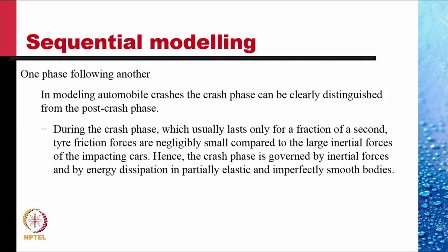During the crash phase, which usually lasts only for a fraction of a second, tire friction forces are negligibly small compared to the large inertial forces of the impacting cars. Hence, the crash phase is governed by inertial forces and by energy dissipation in partially elastic and imperfectly smooth bodies of the cars.